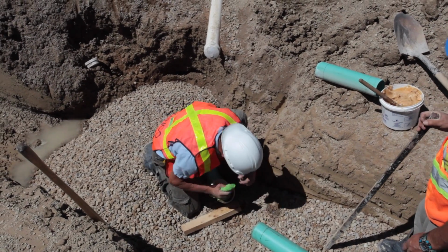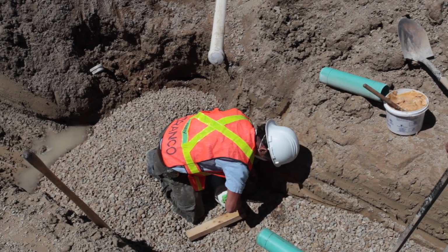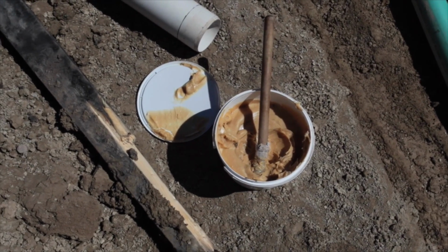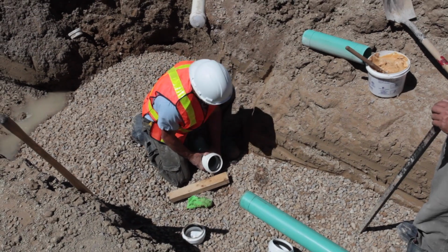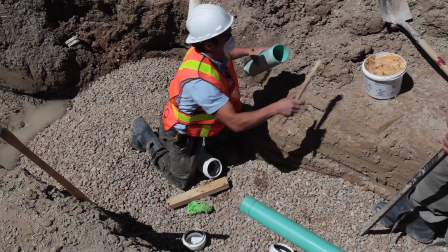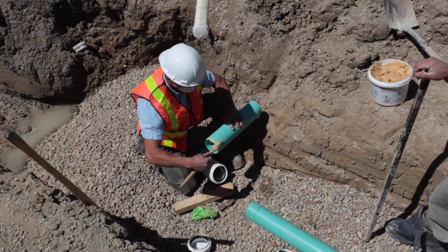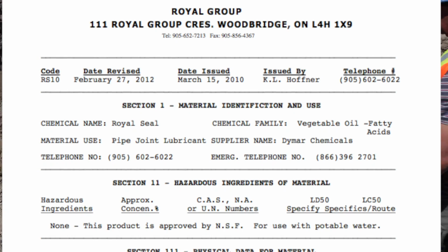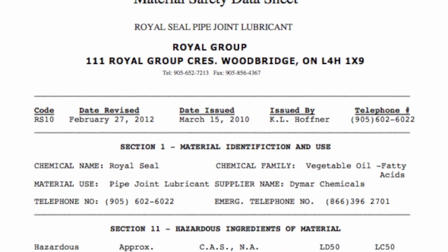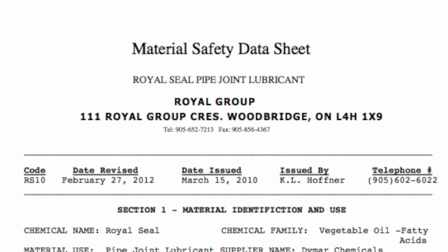Now, at the installation stage, we make sure that all pipe fittings are clean and we check and remove any foreign material. Gasket lubrication is essential and must be applied to the spigot on the bevel cut all the way up to the insert reference mark, plus any additional contact surfaces of the gasket. When working with any chemical or solvent material, it is important to refer to the Material Safety Data Sheet for information on potential hazards and safety practices.